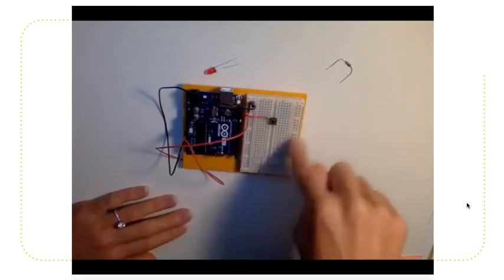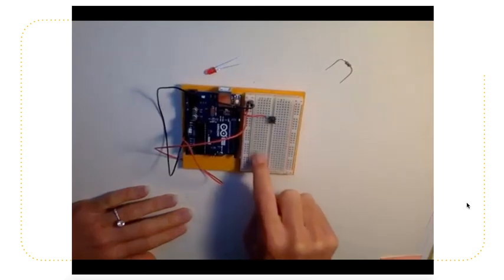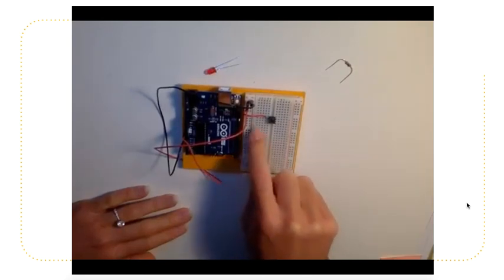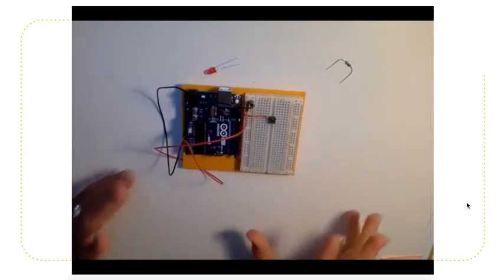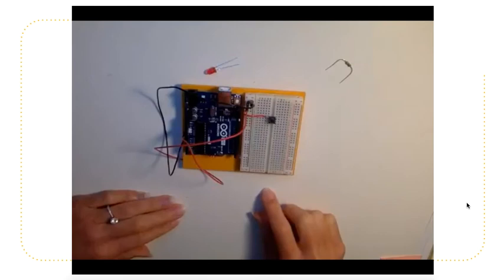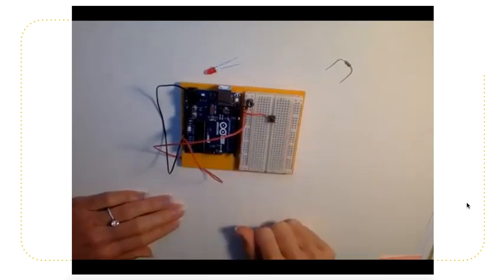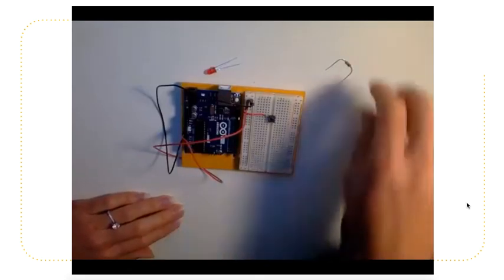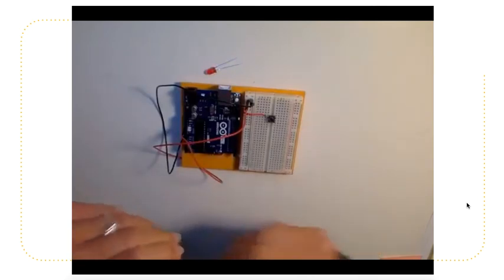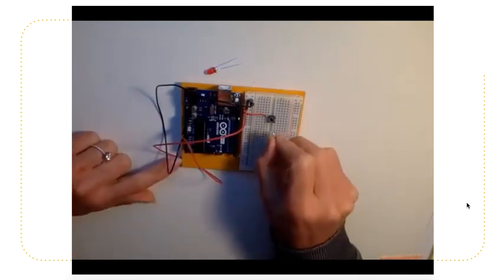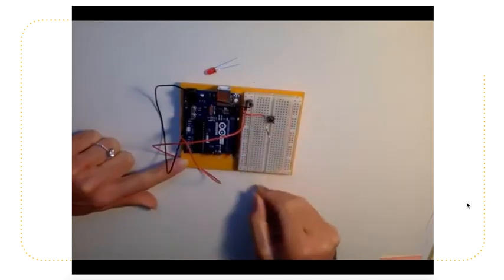The internal pins of the breadboard, not including the negative and positive sides, are wired horizontally. So all 5 of those pins wired horizontally are connected to each other through a metal strip under the breadboard. So right now I have the positive side of the wire connected to one side of the switch. Next, I always like to put my resistor before I put any LED. So I'm going to connect the other side of the push button switch to one side of the resistor.